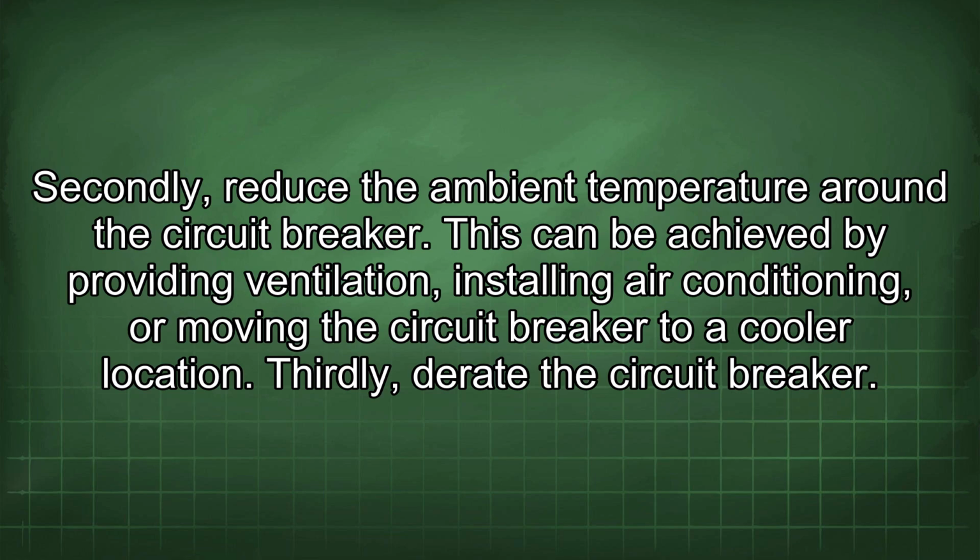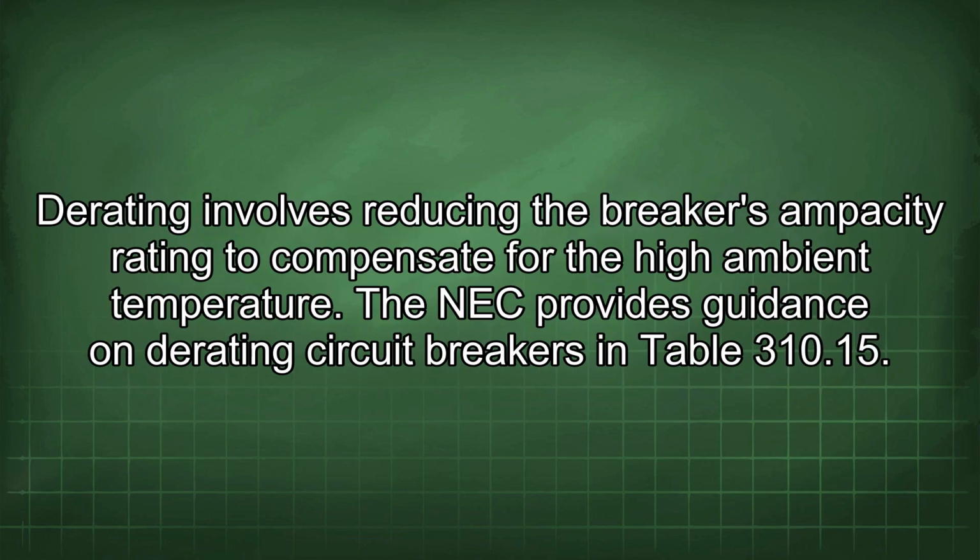Thirdly, derate the circuit breaker. Derating involves reducing the breaker's ampacity rating to compensate for the high ambient temperature. The NEC provides guidance on derating circuit breakers in Table 310.15.